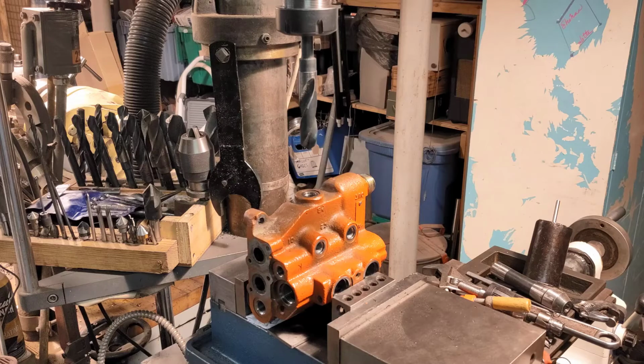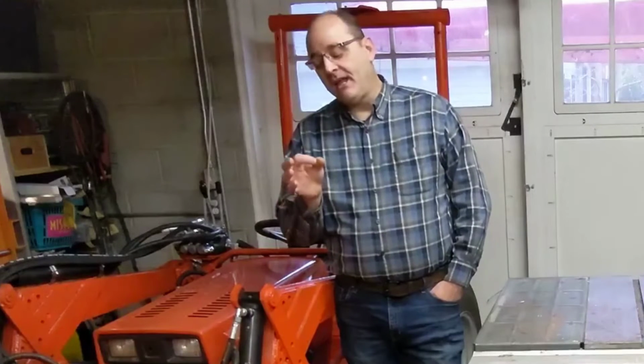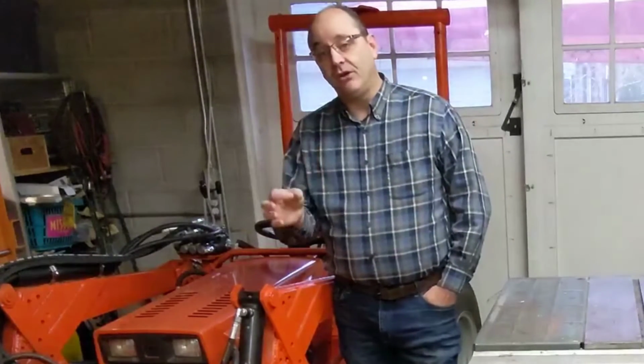I removed and completely disassembled the travel control valve. I took lots of pictures, made careful notes of what went where. I cleaned out the existing hole that leads to the boss marked PB and examined the interior of it just to confirm that the internal cavities matched up with the sketches and photos that I'm working from. There were no big surprises. It looked inside the way I expected it to look.